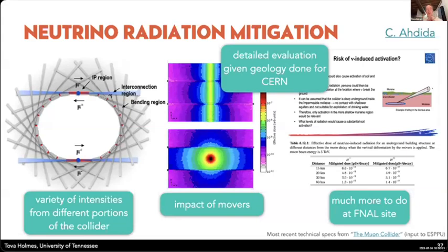Yeah, absolutely. So the high field magnet facility in Florida has been making magnets at this scale. The main thing that you need to do is to have a very small bore for these. So the idea is to only use these at the very end of a cooling channel, where your beam is compressed enough that you don't need a huge bore for that, plus the shielding from it flying all over the place. So this is only something you would consider doing at the very end of that cooling channel. It's still a challenging magnet to make, but it's not as crazy as it sounds if you're used to high field magnets.